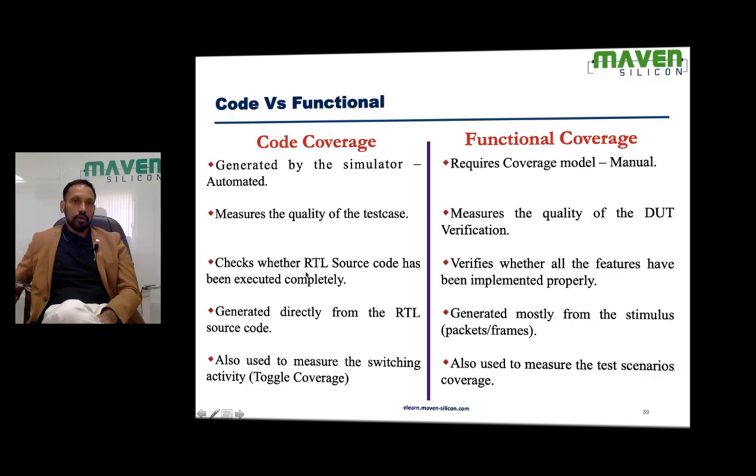And we can also use code coverage to measure the switching activity. If we want to calculate the power consumption during switching transitions, then we can apply code coverage and measure the activity, switching transitions. And functional coverage can also be used to measure the test scenarios coverage.